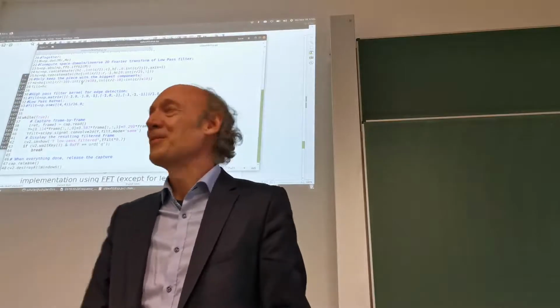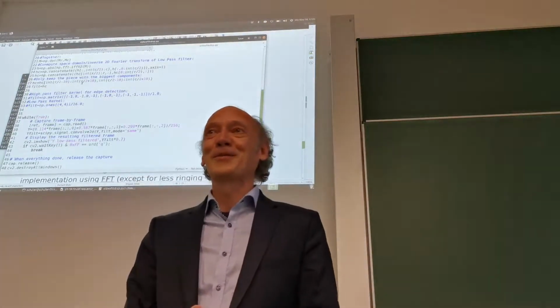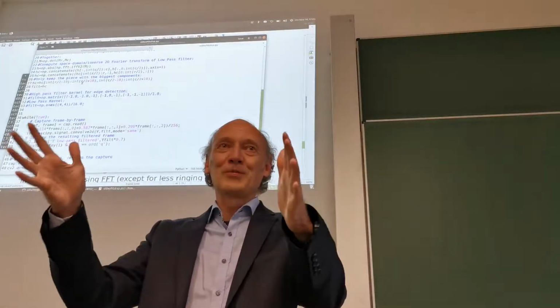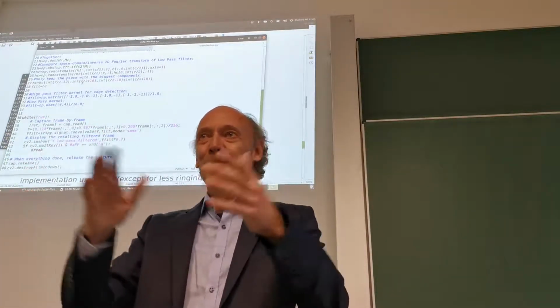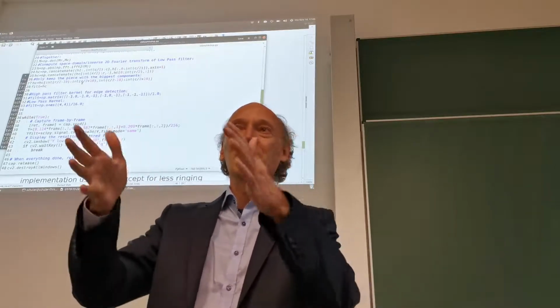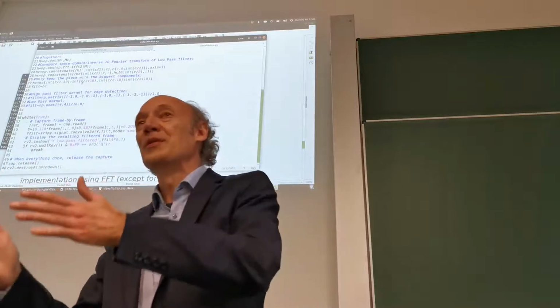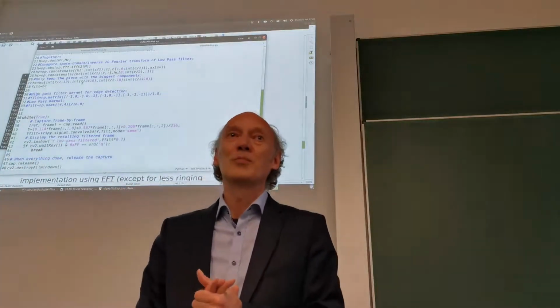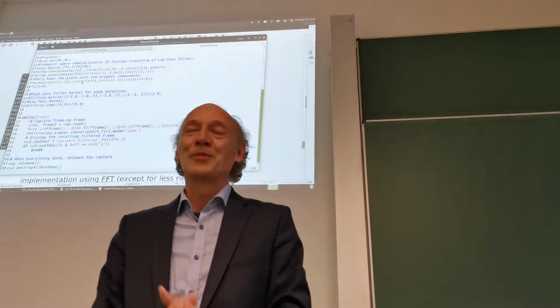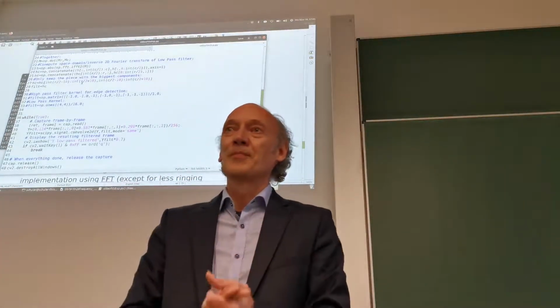And that's why we basically have almost no ringing left, because I cut those ripples which are responsible for this ringing away. And that's also why we get a different result. Cutting off those ends means we now do something similar but different from what we did before. Right? We still do low-pass filtering, but a different low-pass filtering.